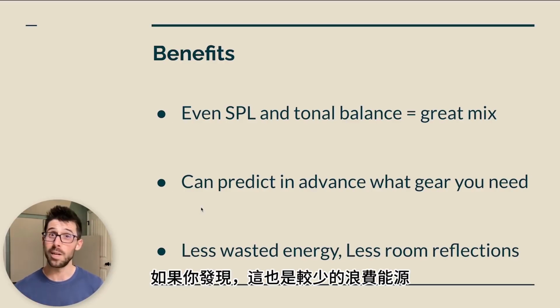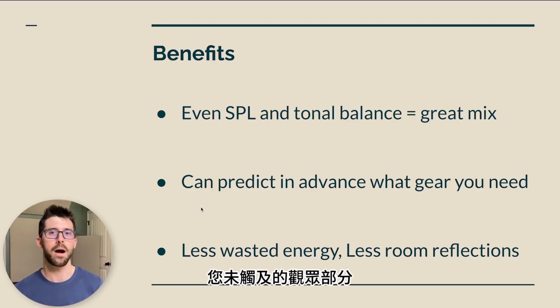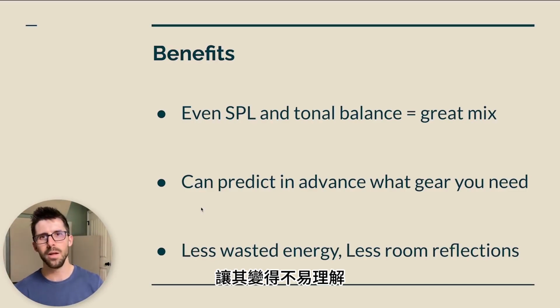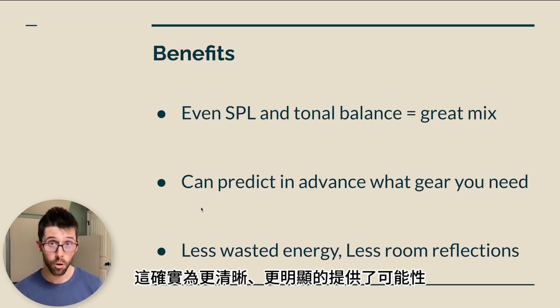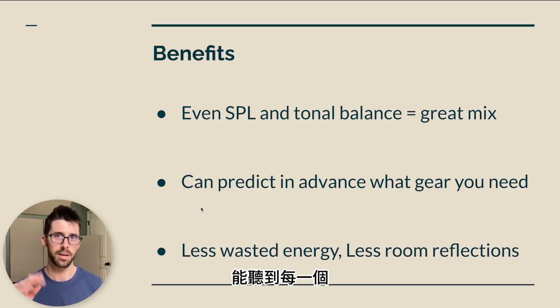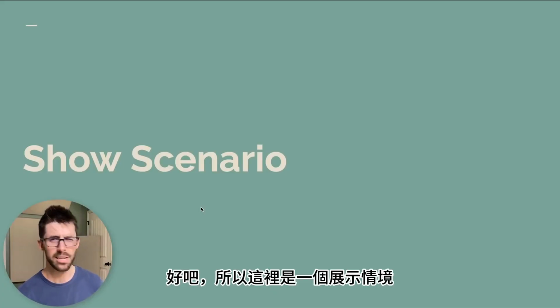And it's also less wasted energy. If you find the perfect speaker to cover a perfect amount of your audience, you're not spraying all over the walls, you're not making it less intelligible. It really makes for a clearer, more intelligible experience. And this is really important on corporate shows, when being able to hear every single consonant and vowel, for that matter, is really important.